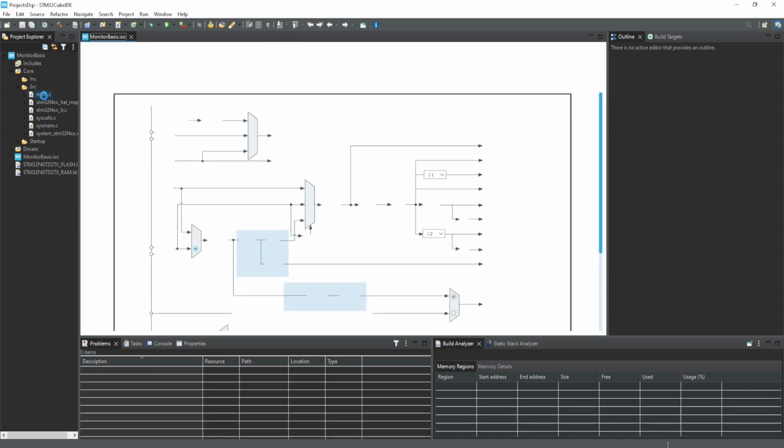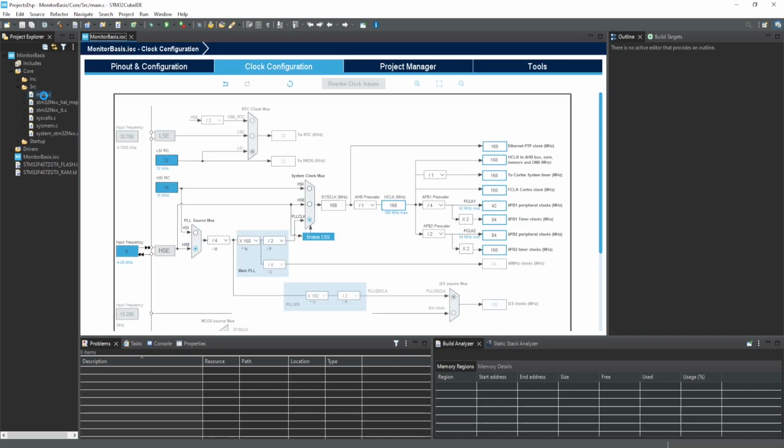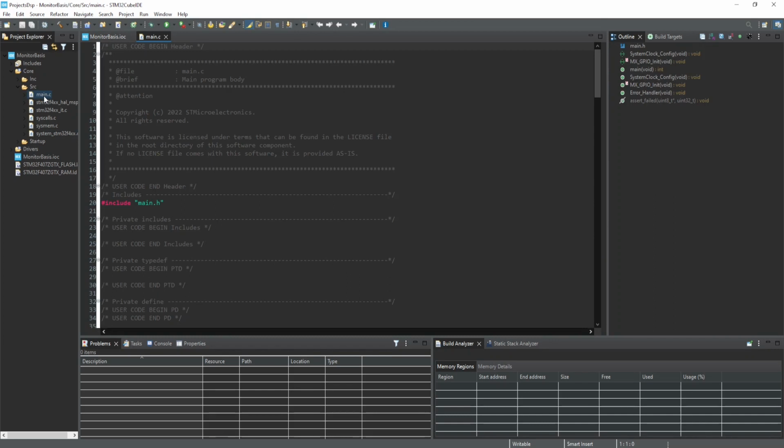So I'm gonna open here the main.c and I'm gonna generate some basic code, some basic projects in order to connect some project variables to the Cube monitor, some input variables to receive information from an input spreadsheet, process those variables, generate some output variables, and connect these variables to the Cube monitor to generate an output spreadsheet.